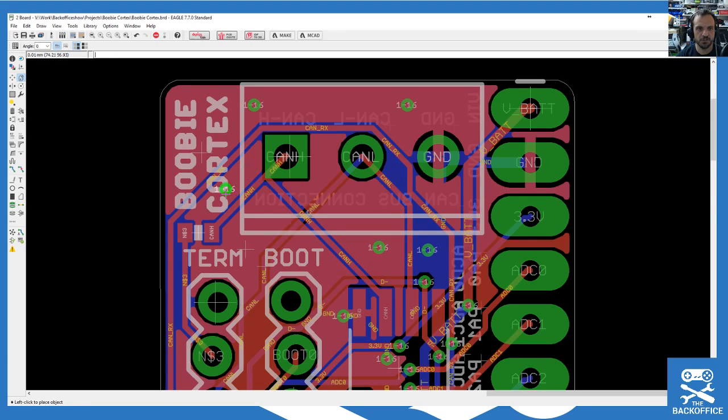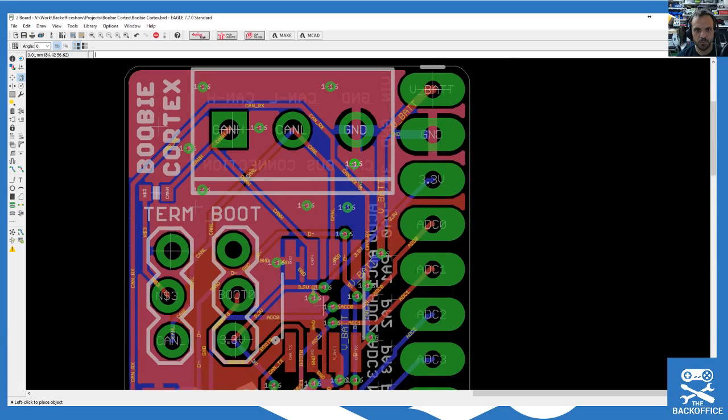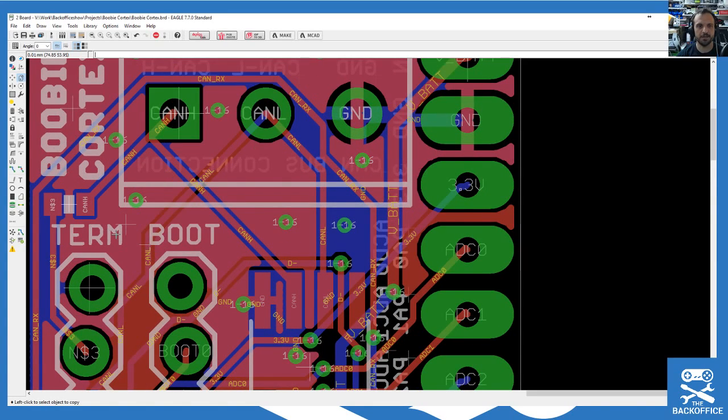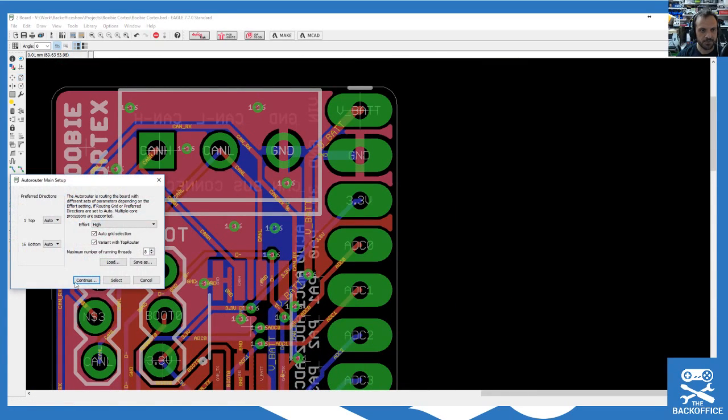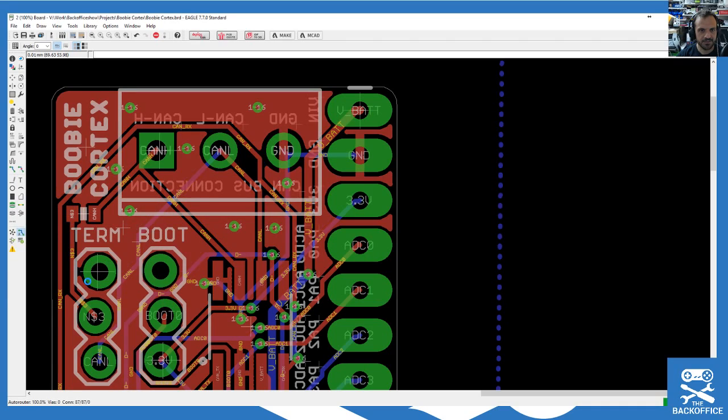If they're not charging you for the vias, then don't skimp on them, because otherwise you're creating basically antennas. So just put them wherever you want, and I'll show you why we do this. I'm just going to pop one there to show you what you do. Hit auto route, hit continue, and you see it kind of reevaluates. Well, it's taken its time this time.